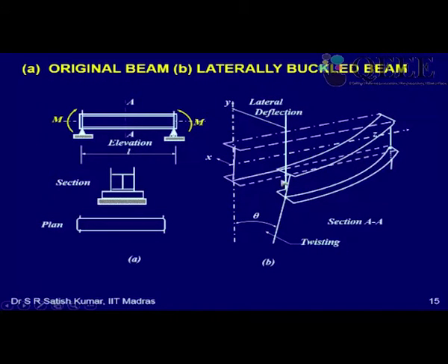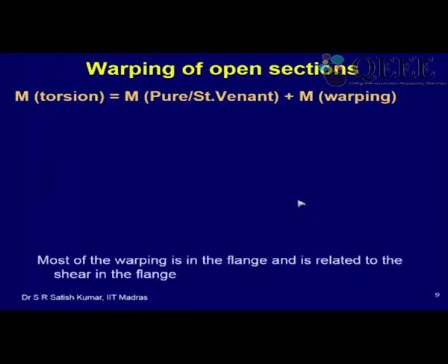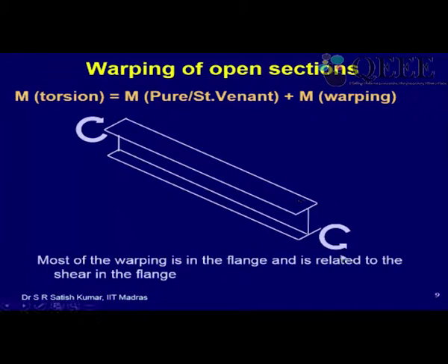So if I want to brace the top flange, directly between two parallel beams, I can give some bracing like that in plan. But then if I want to brace the bottom flange also, what I may have to do is, okay, let's use this as the I section. From the bottom flange, we will give a member which goes inclined and gets connected to the purlins which are running transverse to this beam, right?